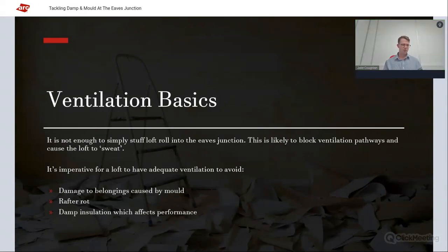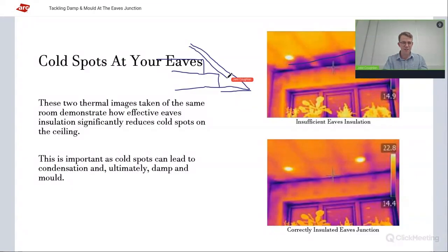And the ventilation there, I touched on it with the surprising case study. We need to consider ventilation in all retrofit, especially past 2035 projects. But the Eaves Insulator specifically deals with ventilation in the loft. So my surprise in this scenario was they left this gap open. It was an eaves ventilated property and a cold loft, and they kept this open, which caused a thermal bridging problem, but they didn't have a ventilation problem.